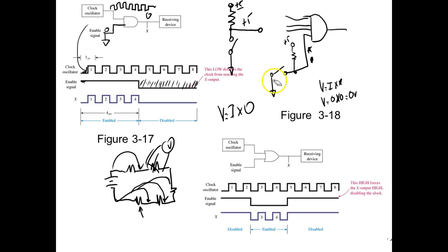So what we've done is I've closed this. If I come up here and close this switch, I've closed the gate. Those other inputs don't make any difference. If I come over here and open this switch, then it acts like a 3-input AND gate. But I've added this 4th switch. I'm using it for an enable or a disable. So if I close it, I don't care what the other inputs are, right? You understand? If I open it, then it's going to respond to those other 3 inputs.